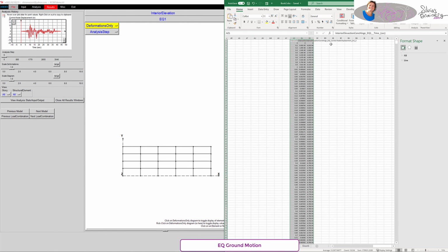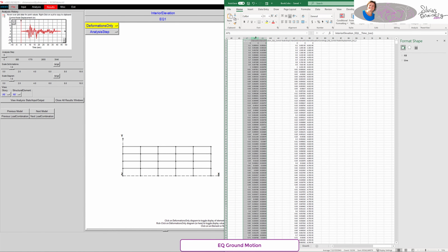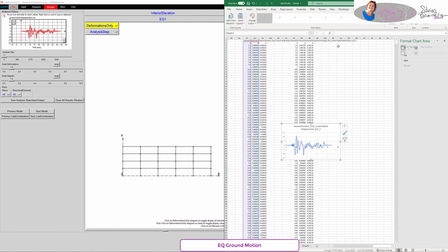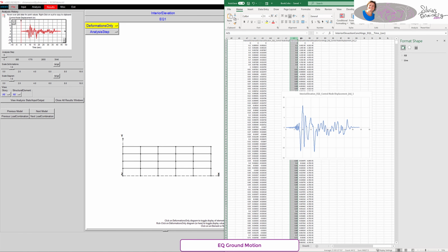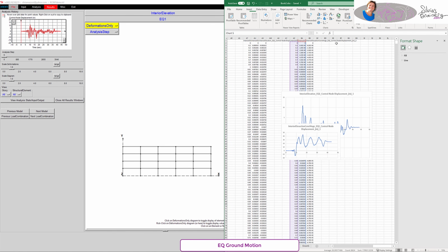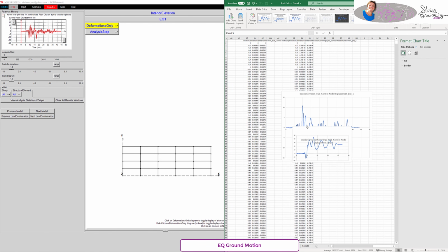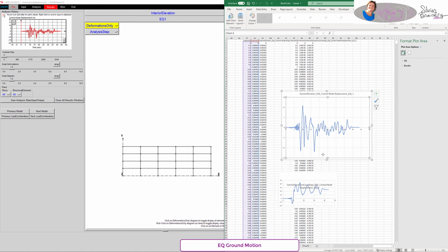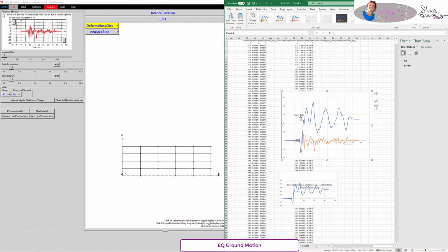What I'm going to do now is plot just the two different displacement responses and show that the fiber section does not capture the offset while the hinge model does. But it really depends. It just happens to be the case today. You really have to evaluate many different models. And this is just to show that they do give different results.